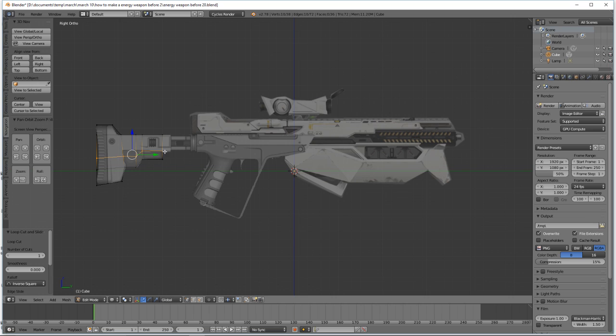I prefer for this line to be straight rather than bent up like that. So what I'm going to do is press S to scale on the Z axis 0, and then left click to lock that in, and then that technique just made this line straight. So now that it's like that, I'm going to pull up some like that. I'm then going to press A to deselect.